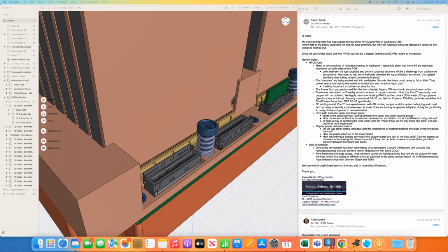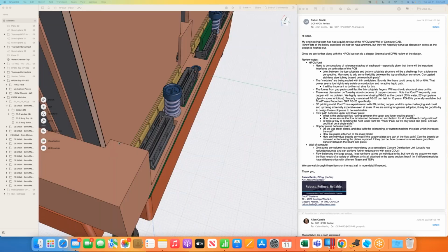Now, what we did is we had jigs where you'd put all of the connectors into the jig and they would be reflowed onto the PCB together. So at least relative to each other, and they would also go into alignment holes in the PCB itself. So you would get a pretty good reflow in terms of the accuracy there, but there is obviously tolerance there. And to your point, the tolerance of that versus the tolerances inside the actual gaps here and the mating are going to be pretty important.